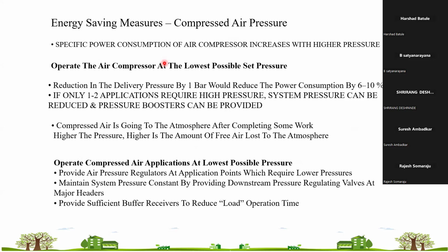Your hot air temperature will be down if you are using a waste heat recovery medium, not in the flue gas or something like that, but your oil temperature should be lower. Your compressor work will be on the lower side, so your discharge temperature is automatically on the lower side.